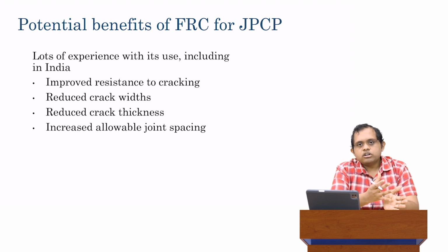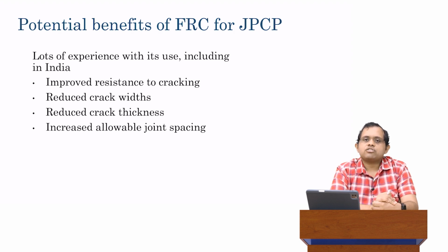There are still ways to do it, but given the vast volumes required for rigid pavements, it's difficult. Whereas microfibers do not have this problem, they're relatively easy to mix around, you don't need very specialized equipment either, and it can be done in large volumes. So mostly in rigid pavements of JPCP applications, we tend to make a lot of use of micro FRC.